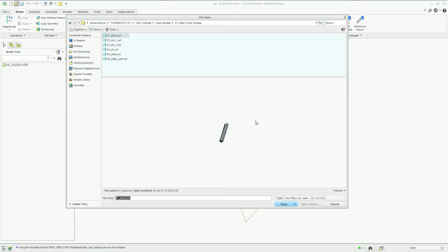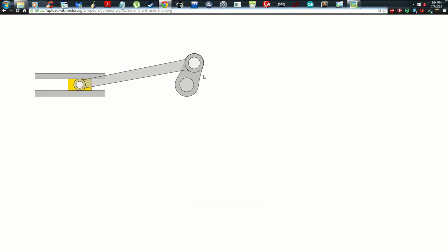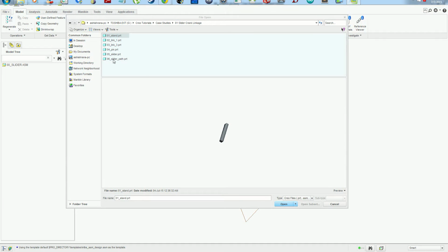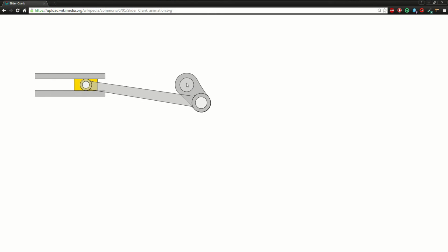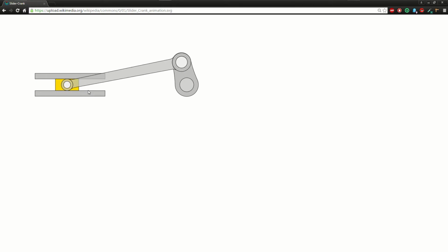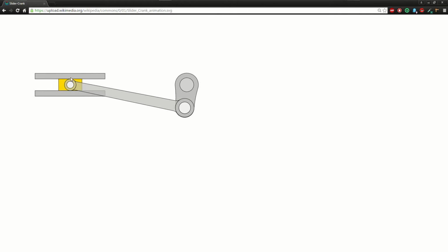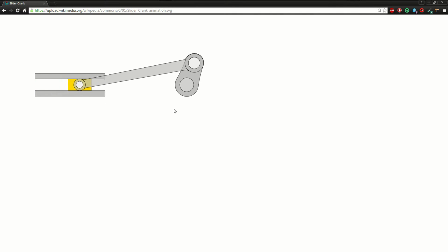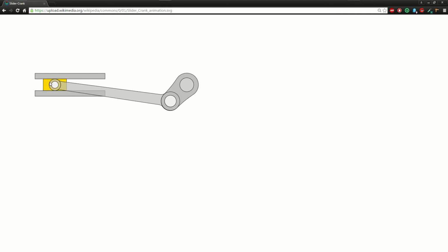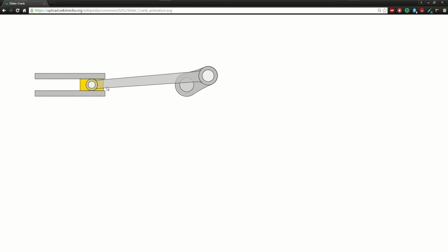These are the parts that I've made, and I'm gonna compare them side by side to this linkage. So let's look at this linkage first. We have a pin around which we have this link that's rotating. That link is connected to this driven link, this long one, and it's connected through a pin inside of it right there. And then we have a slider that's constrained by a sliding path, and the rotation of this is attached. This driven link is attached to the slider, and rotation of this link is causing this motion of sliding